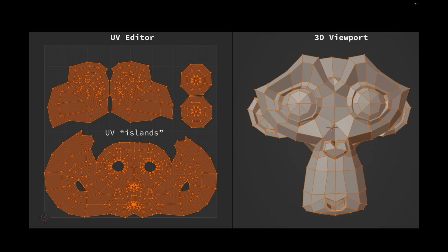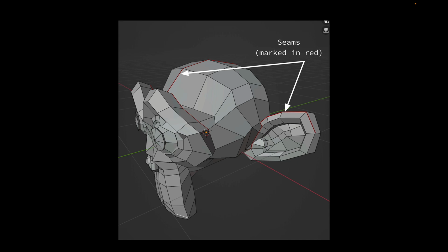It's a little bit stretched out when it gets flattened, but you can see where the eyes are, and then where the mouth and nose are on the UVs on the left. And to create that UV layout, I went ahead and marked these seams so that when it automatically unfolded our object, or unwrapped as it's called, it knew how to separate those UVs out.